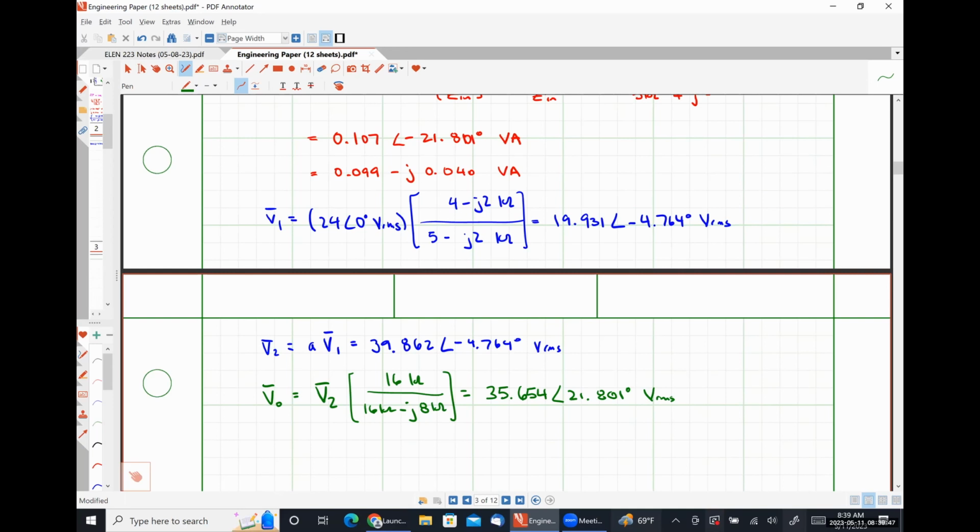When we get into our second power class next winter, what we're going to do to be as lazy as possible, actually, is when we develop our model for magnetic circuits and transformers, we are going to include an ideal transformer in our model for a practical transformer so that we can easily reflect connected impedances back and forth between the primary and secondary, just to make our lives a little bit easier. So we're effectively going to combine these two topics into one single model that can be used to account for any type of losses we might see in a real transformer. All right, so that's the last thing that I wanted to talk about for today.